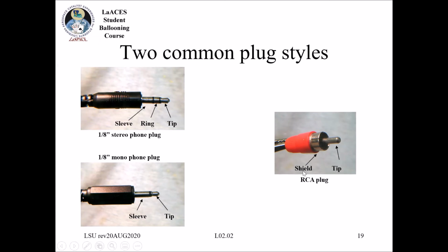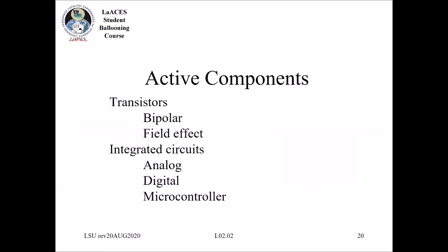Although I would say if you do have power on this RCA plug, just be aware that that voltage, the positive voltage, if it's on the tip, it's just hanging out. So if that thing accidentally touches ground or something like that, then you can certainly have problems. And truthfully, with all of these things, if somehow it comes into contact with a piece of metal across it, and you've got a ground and a voltage touching, you're going to end up with some problem there. So just be aware with those things.